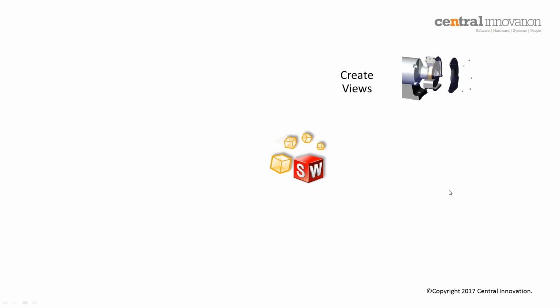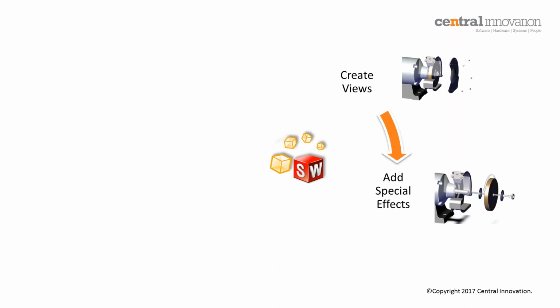In the demo, I'll start off by importing an assembly of a bench grinder, which I'm going to be showing you, and I'm going to import it directly into SolidWorks Composer. I'll be creating views, and I'll show you how quick that is. After that, I'll be adding some special effects, which will include path lines and some more arrows to show directions and other things, and also some detailed views.